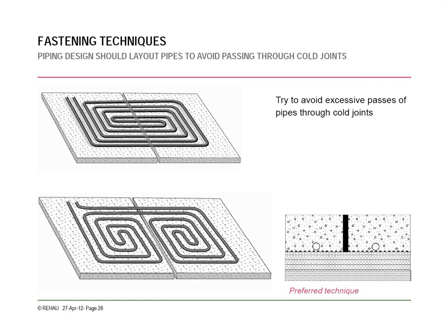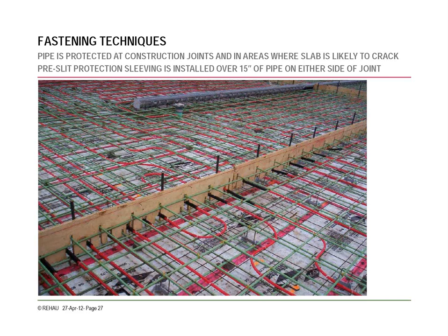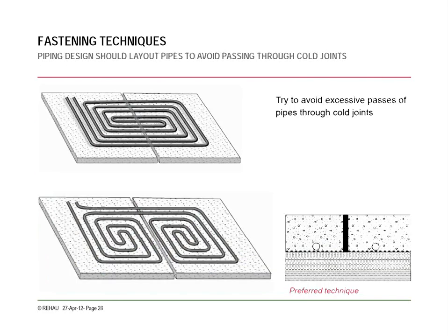Again, also on that note, if you know where the joints are going to be, you want to do your best to run the fewest passes through the actual joint. On that previous picture, you'll note that they could have easily just gone the other way here and had one or two little intrusions. Instead, they had all of them, like the top picture here.